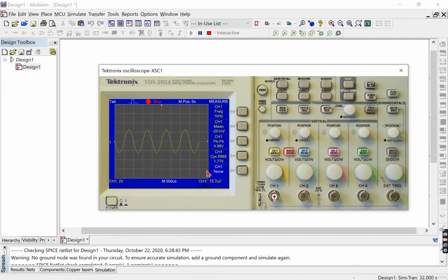So now the screen currently shows readings of the signal under AC settings or AC coupling. To change the coupling of the oscilloscope, we will press on the channel that we have the signal connected to. In our case, it's channel 1. And then it's actually DC coupling currently. So to change the coupling of a channel, press on the channel menu, for example, channel 1 menu, and then toggle the button here. Currently, I've changed it to AC coupling.